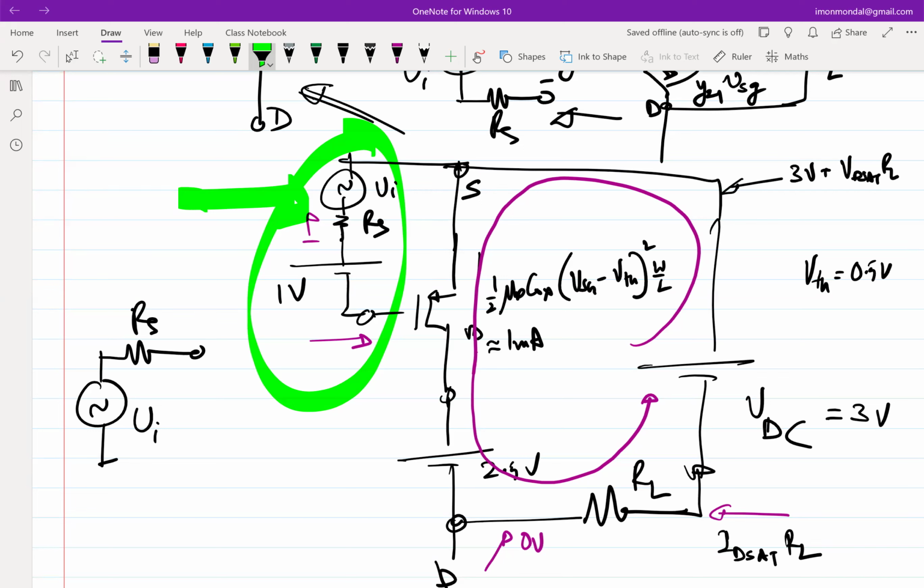Both the source and the supplies were never connected in series. If you recall, all of them were always connected with an implicit ground. You had a black wire which was connected between the machines and had to be connected to the breadboard. So that reference wire was the ground. So all equipment, all sources should have a common ground.